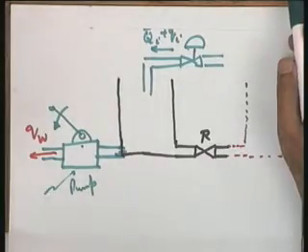Disturbance, I am calling it from the point of view of modeling, because this, what is a disturbance? Disturbance word, you just recall the bathroom toilet tank example we had taken. The flow which is your useful flow, we had called it a disturbance, because this fitted very well into our mathematical model, because we modeled that particular situation as a regulator system. The idea was to regulate the system to a constant head level, to a constant tank level.